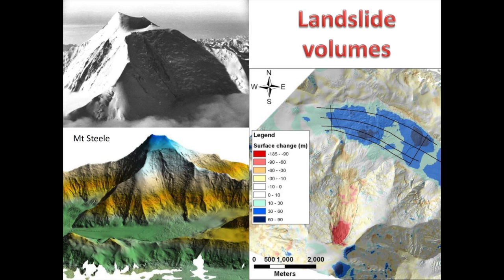We just happened to be there, so we flew. It was actually quite a challenging survey, because you're up at over 20,000 feet in an unpressurized survey plane, and the range from the top of the mountain all the way down to the bottom was approaching 3,000 meters, or 3 kilometers, which is the vertical range capability of the LiDAR sensor that we had. So clearly we were unable to survey the top and the bottom of the mountain at the same time. So we essentially had to fly lines and stagger the lines down all the way in order to capture this